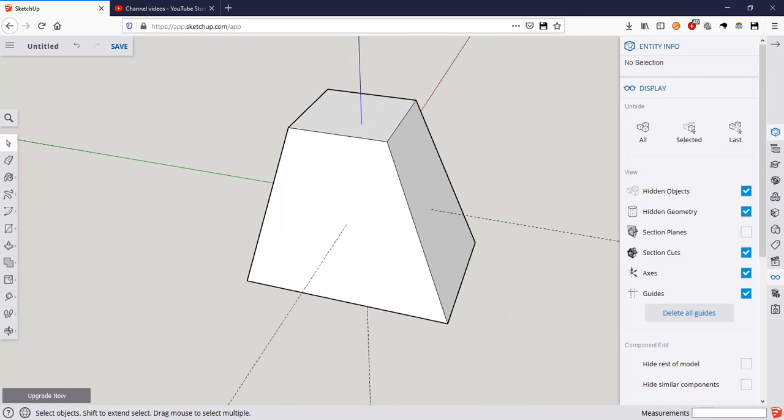If that needed to be 50 millimeters, okay, measure, Control-T, hit T, hold Control when you click the last data point, type in 50 and then mm.